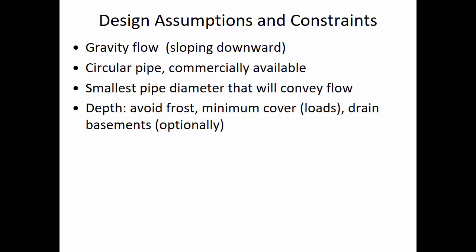So first of all, before I go any further, does everybody understand why the velocity would be low in a shallow flow pipe? If you think about the friction, it's because of contact between the water and the pipe material. Here you just have more contact. We don't have this area in the middle where there's less resistance. So here you have more resistance, lower velocity.